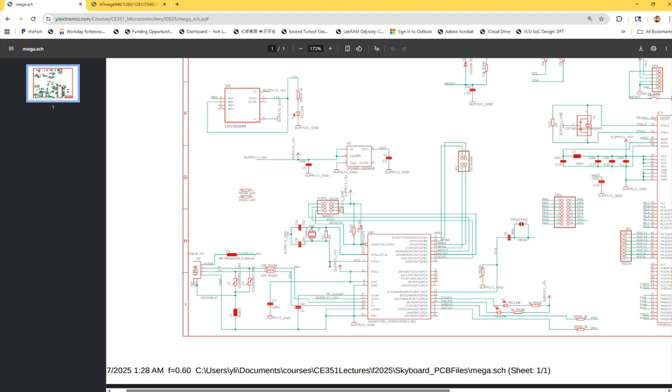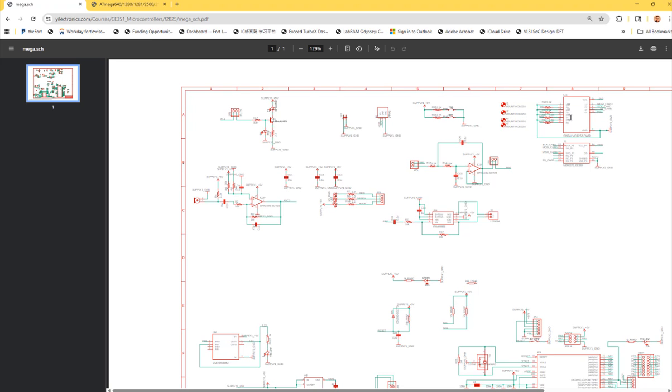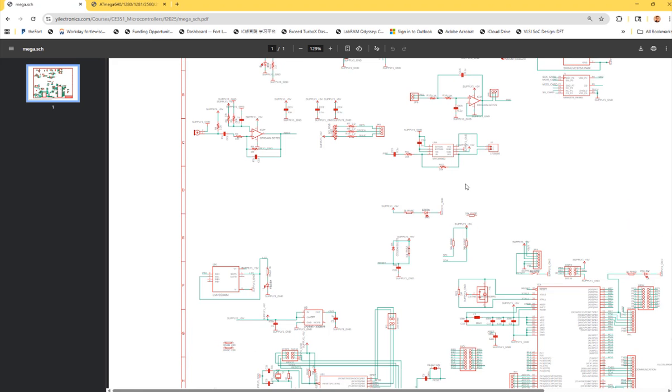But for this time, during the interview, whenever they're asking you about any projects you have done, right? Talk about the projects. You can tell them, I just used the USB to power up my circuit, which is fine. So USBs are always 5 volts, keep in mind. It's always 5 volts. Okay? So if you have a circuit component which requires 3.3 volts, you will need a regulator on it. But I don't think we need a regulator here. If you use SD cards, there might be a regulator inside with a voltage shifter on the top. But this is something we'll talk about later, okay? So we're not getting there yet.